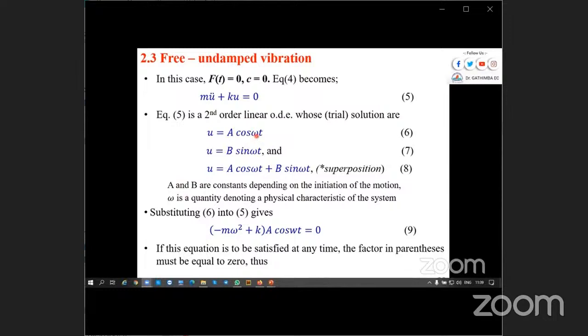When our motion is moving to and fro, when our structure is vibrating, there is what we call the vibration. We call it the frequency of vibration. So this physical quantity, omega, is called the natural or the angular frequency. We are also going to see how, from the angular frequency, we get the linear frequency. Omega is expressed in rad per second.